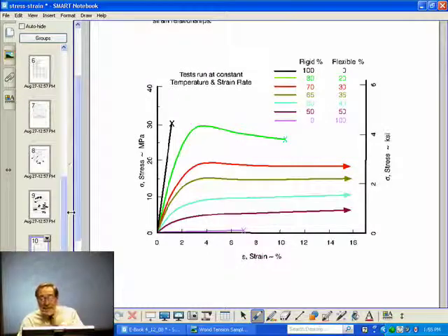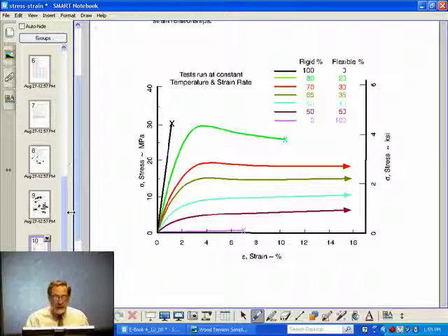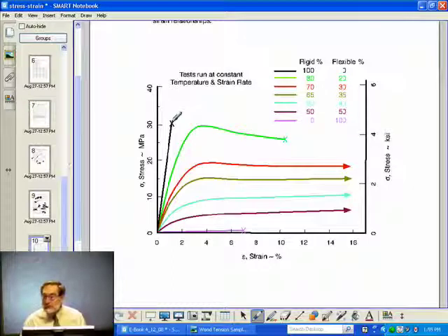A little bit more, though, is here's how stress strain curves can happen. This one happens to be percent because the strains were huge. Huge. I took some rigid polyester and some what's called flexible polyester, and I ran the test on the rigid, which is this one here, and that's like glass. The X means it broke. It's absolutely straight and broke. The flexible is this little line right down here at the bottom. It has a very, very low E.